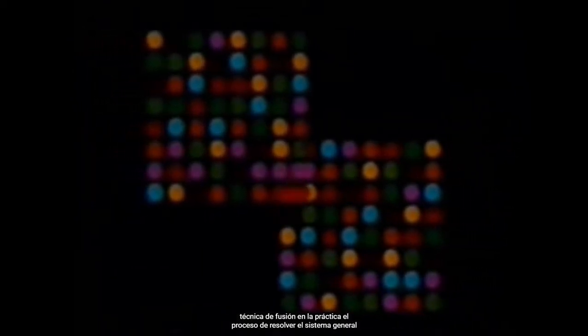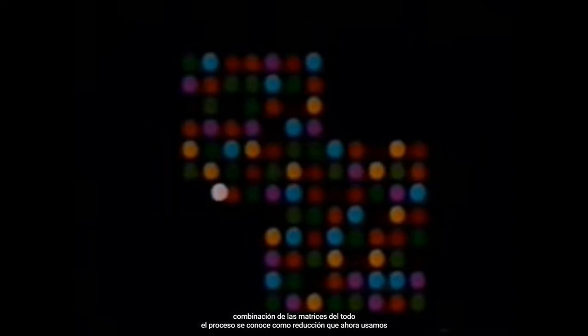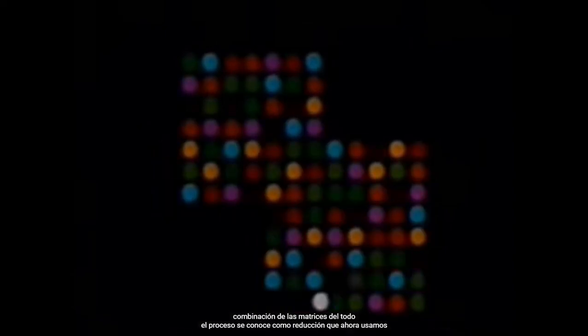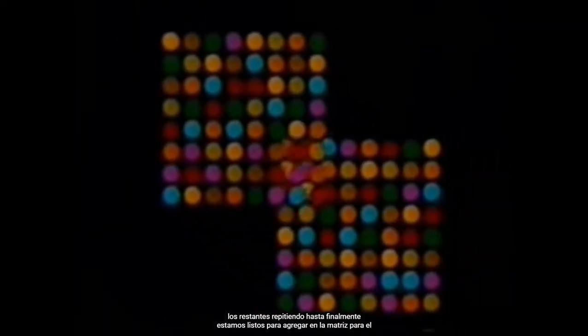In practice, the process of solving the overall system equation is done concurrently with the combining of the matrices. The whole process is known as reduction. We now use a standard procedure to eliminate part of the matrix. The rows of the matrix represent a set of simultaneous equations. We solve the first equation and substitute the solution in the remaining ones, repeating until finally we're ready to add on the matrix for the next element.